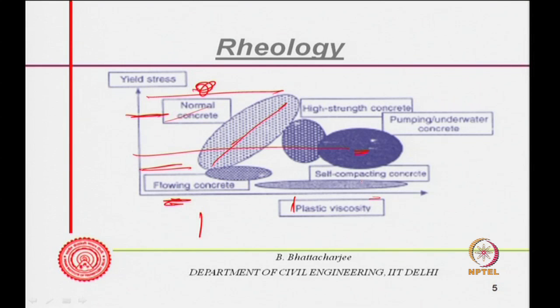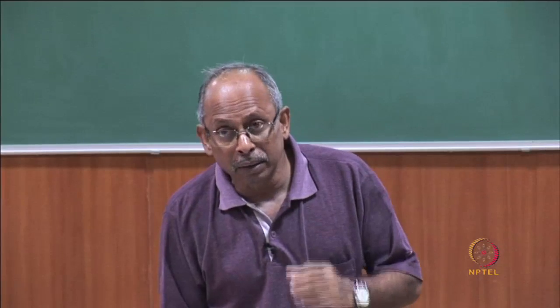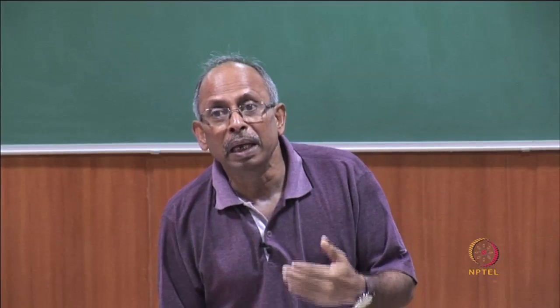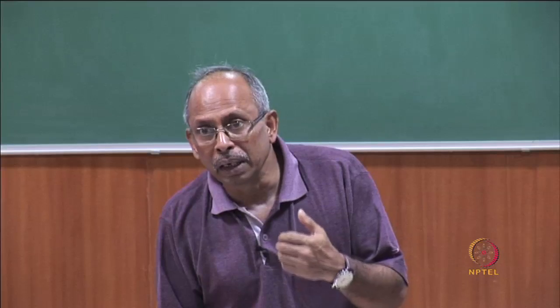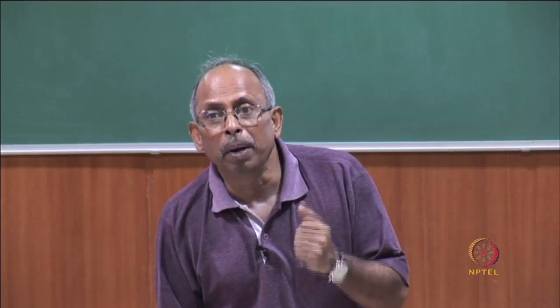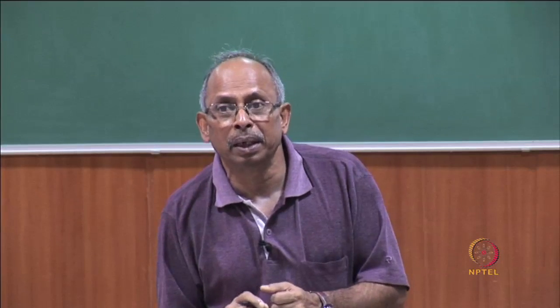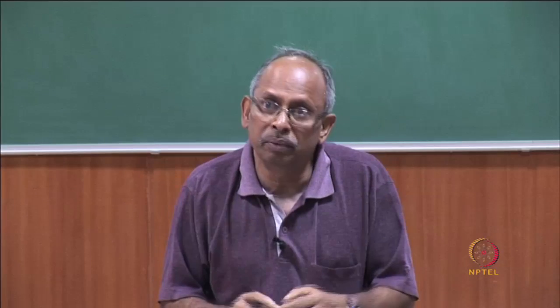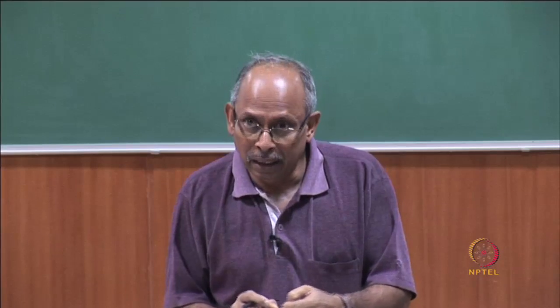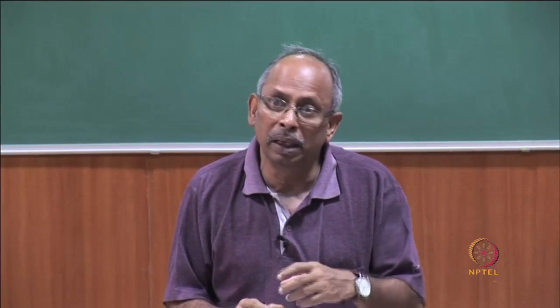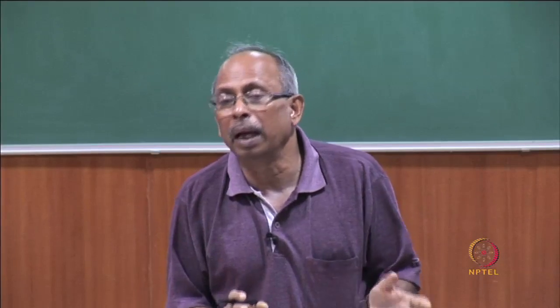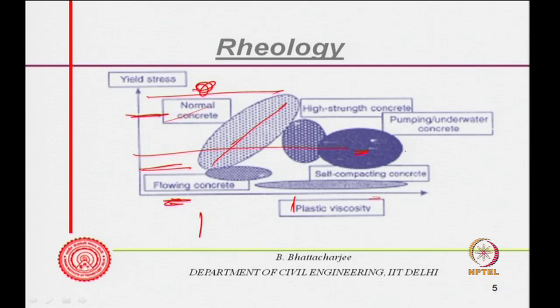Why is the yield shear stress low? It can withstand some amount of yield shear stress because you will be pumping it. There is a pumping pressure, only it should remain cohesive and should not segregate. Disturbed relative motion between particles should not be there within it, but it must form a plug and then move. So, that is pumpable concrete.